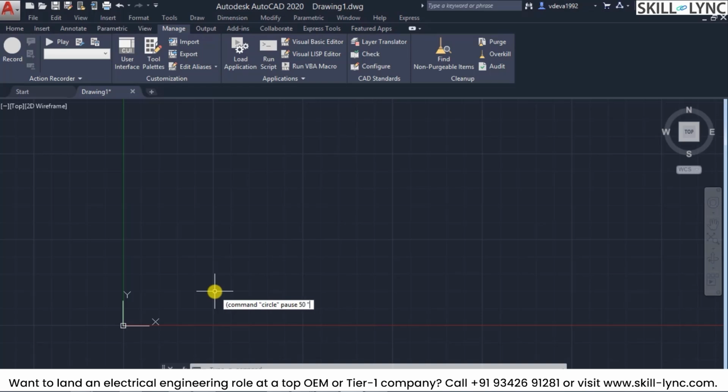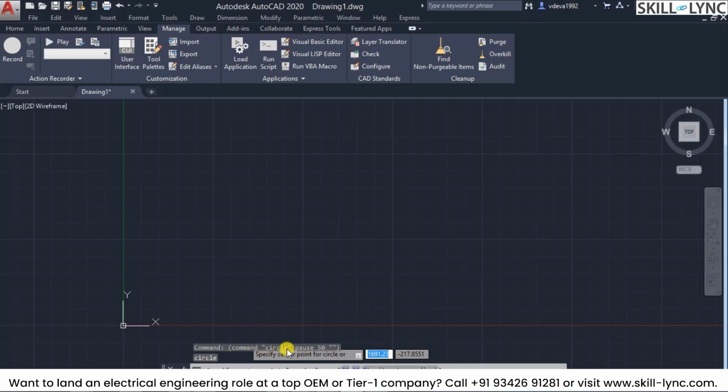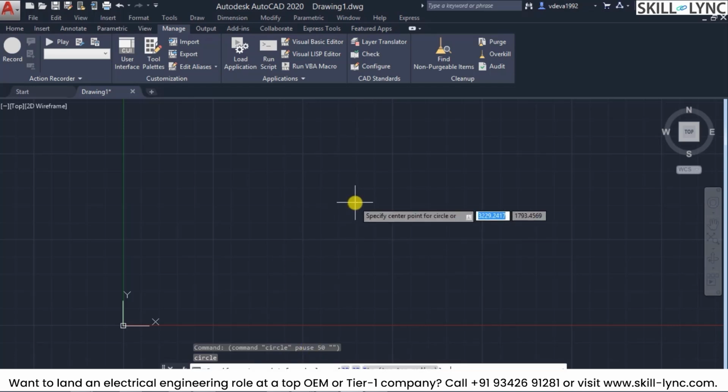and then space, close it out, that is giving an enter key by using the double quotes, and then close it with enter. Now click on enter. Now you can see that the circle command has been executed. You can see here the command is circle. It has been called, and as the input is a pause, AutoCAD prompts for specification of the center point.